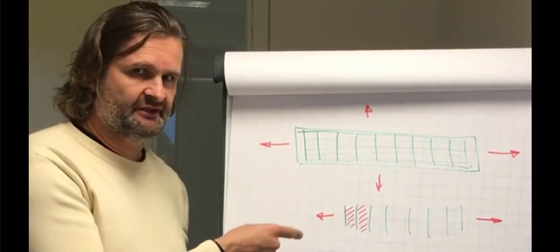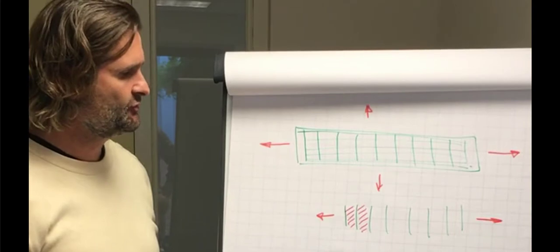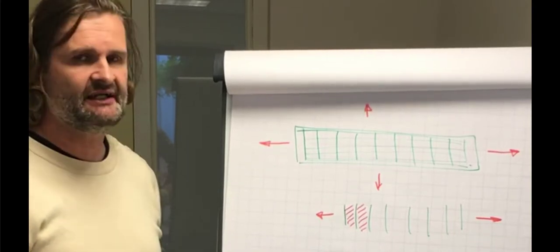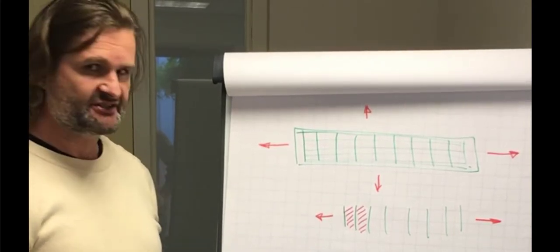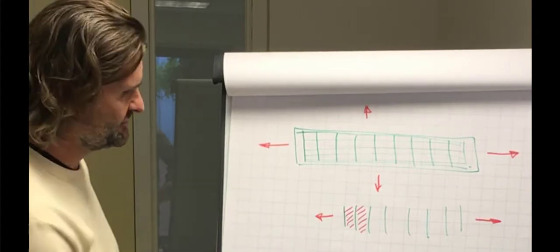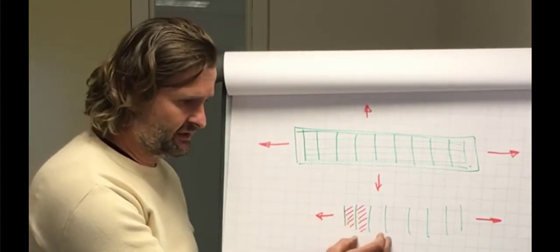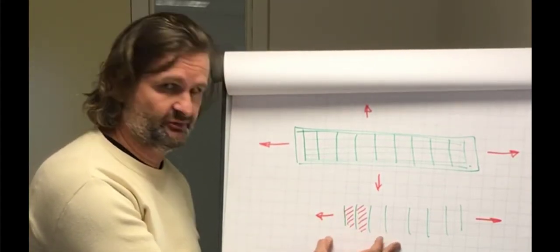This is the cause of it, and what we can do to mitigate this a little bit is to get resin that is a little bit more flexible. So if the resin is more flexible, we can allow for more deformation in this direction without failure.